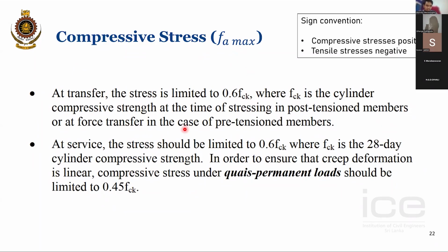At the service stage, that is after you place this beam on the structure and apply the load, again the stress is limited to 0.6 times fck, but now fck is the 28 days compressive strength. Right? There's a difference between fck at transfer and fck at service.